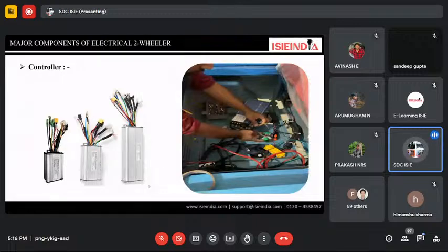Inside the controller also, there are a lot of wires along with the connections, like those for the phase sequence delivering the output which is coming from the MOSFETs. The MOSFETs act as an inverter circuit in the internal part of the controller, where we give a DC power supply but get a trapezoidal waveform. So it can fulfill whatever pole mounting is created on the motor, for a north pole or a south pole, we are changing the polarities of the power supply, which is given by the MOSFETs present inside the controller only. So we can call the controller a driver circuit of the EVs.